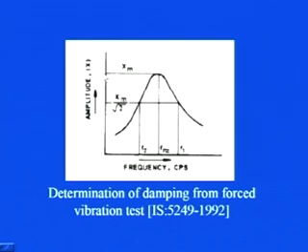If xm represents the peak amplitude of the system, the corresponding frequency is fnz, the natural frequency of the system. If I divide xm by square root of 2 or multiply it by 0.707, it is one and the same thing. Here xm is the peak amplitude, and it gets reduced to this level.